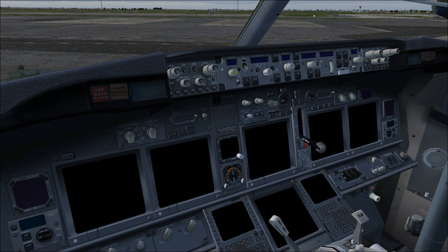The static ports and the pitot tube for backup actually are not controlled by any ADIRU unit. They are directly connected to the standby instrument. Actually, we have a magnetic RMI that is analogic, and the digital ISFD, or integrated standby flight data instrument, that gives us the speed, the altitude, and the attitude of the aircraft in case of a failure of the other systems.